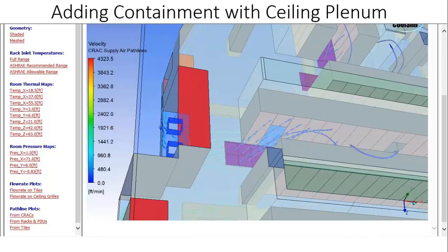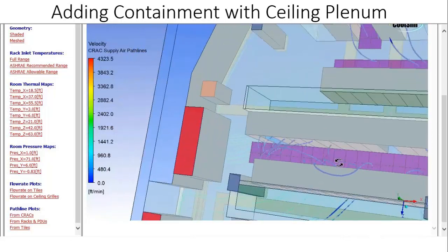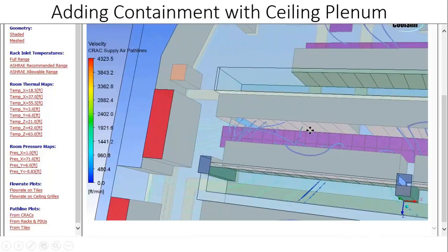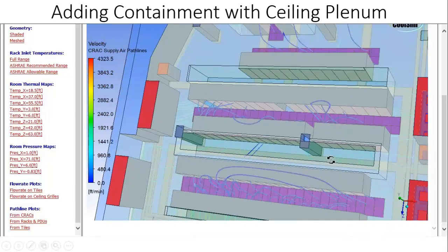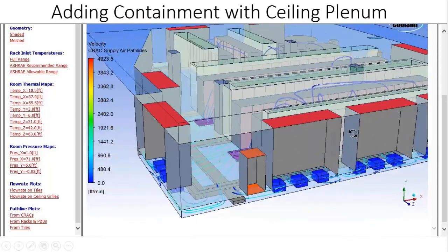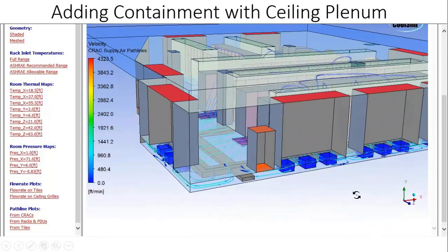So I think you may see more of that, particularly in rooms where the subfloor is not as deep as you would like, and you still need to add capacity, and you'd like to do it without changing the floor because that's a very expensive option. So using profile tiles or finned tiles may be an option that's really worth looking at. There's also the option of using an underfloor fan. There's a lot of things that you can do.